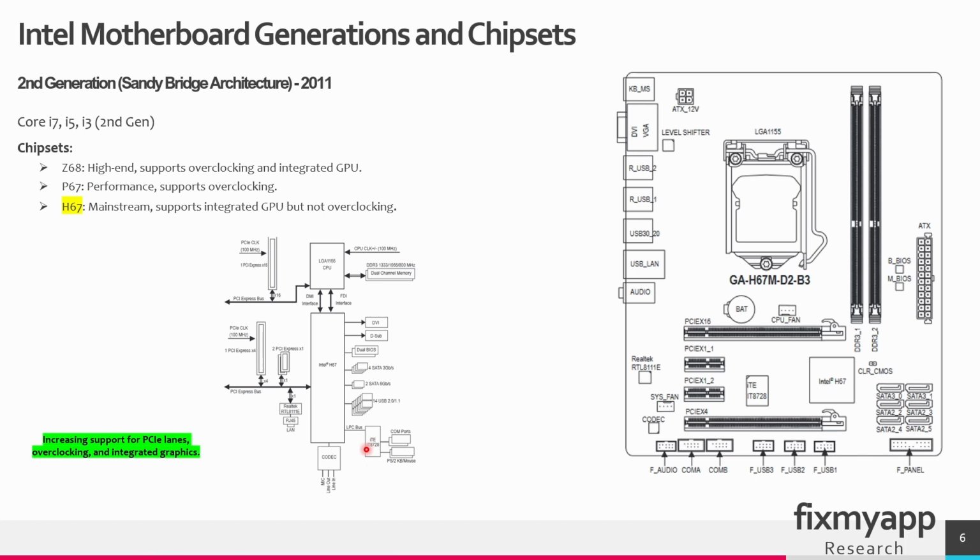This is the Super I/O chip. So the COM ports and the mouse are connected to this chip. This chip communicates with the chipset by a LPC bus. I think it is a low pin count bus. And if you look at the mainboard, you can see that the Super I/O is implemented here. So the mouse connector and the COM ports are connected to this Super I/O. This Super I/O will communicate with the chipset, and from the chipset it will go to the CPU.